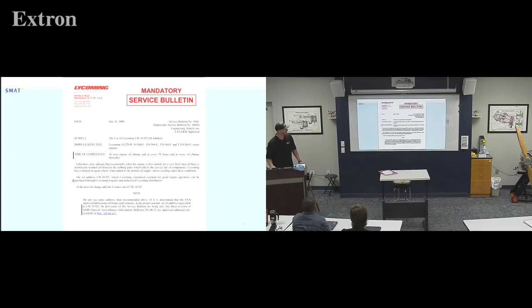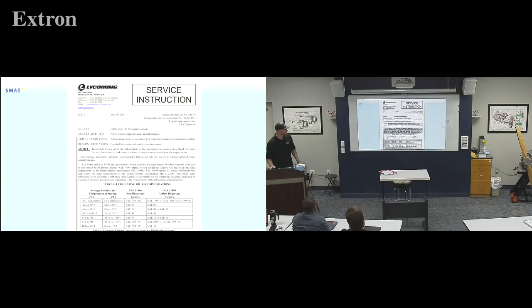All right, mandatory service bulletin. You're going to see all those same numbers up there on the mandatory ones. That one's a service instruction, and that's the one approving the additive, because there were other parts that ask, are you allowed to just put whatever additive in?